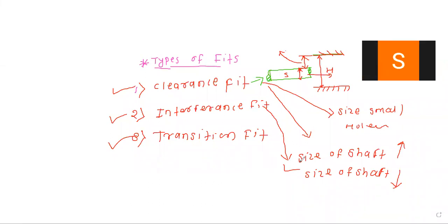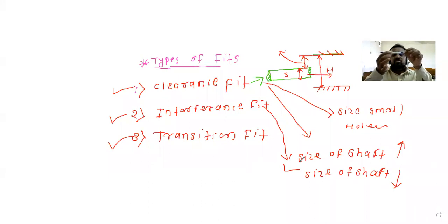Clearance fit. Okay, clearance fit. Just see now. The shaft is easily inserted into the hole, which means in between the two parts there is a small clearance. When your shaft is small and your hole is larger, such a condition is called the clearance fit.